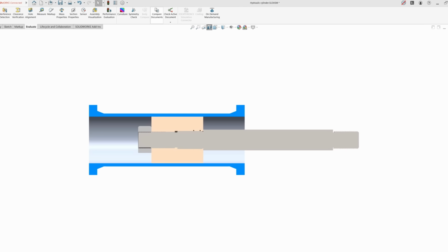So to achieve this, we will guide the rod within the piston by adding a guiding step, considering a 70 mm guiding diameter, and to fix the rod into the cylinder, we can use a threaded step and a nut using the same connection thread M64x3.